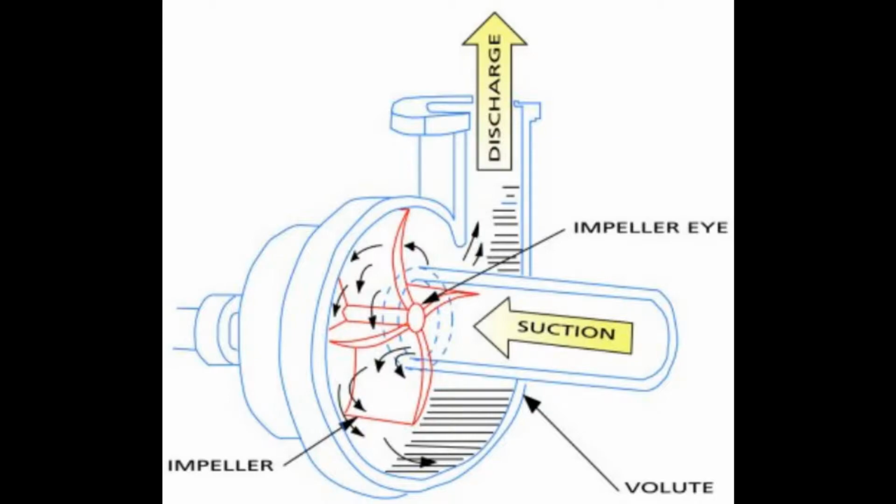The fluid enters the pump impeller along or near to the rotating axis and is accelerated by the impeller, flowing radially outward into a diffuser or volute chamber casing, from where it exits into the downstream piping system.